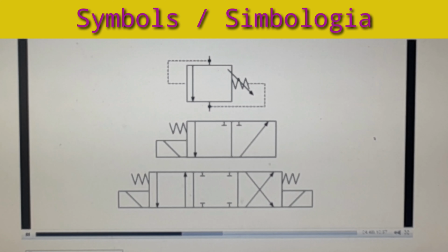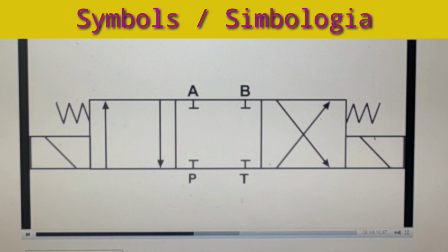Valve examples: pilot operated. Adjustable relief valve. Two-position, three-way, solenoid operated, spring return valve. Three-position, four-way, spring-centered closed, solenoid-operated valve. On this page we are showing 4 different center positions for 3-position 4-way valves. Closed center, where all 4 ports are blocked.